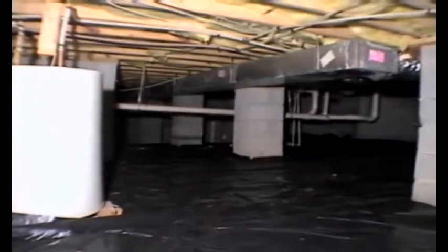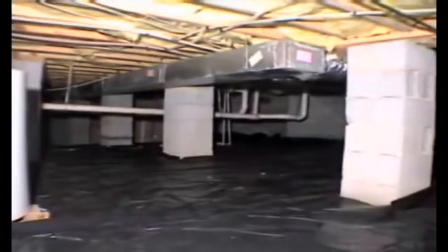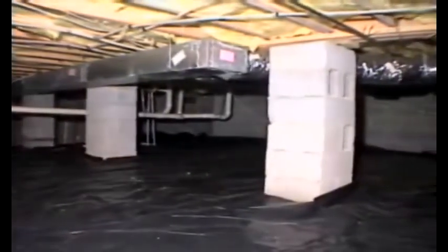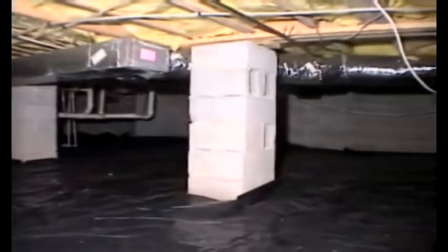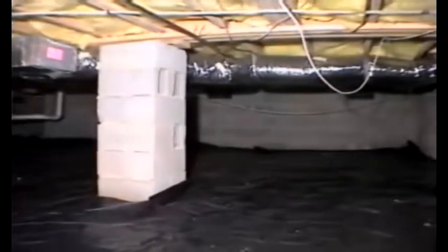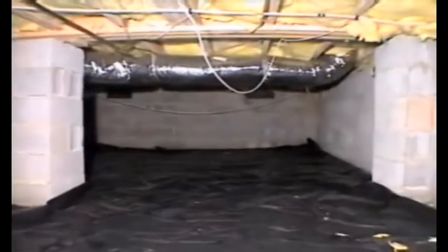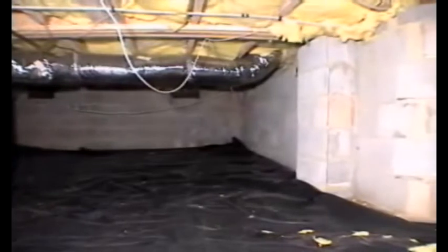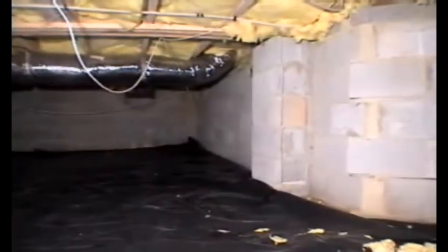These results also bring into question the effectiveness of ground vapor retarders in controlling crawlspace mold. Many building professionals have thought that a full coverage layer of 6 mil poly on the ground was the main strategy needed to control crawlspace moisture. The field test results do not support this belief when it comes to mold prevention. Despite the carefully installed 100% coverage ground poly, excess moisture continues to enter and remain in the wall-vented crawlspaces. This excess moisture creates a damp, mold-friendly climate in humid weather conditions.